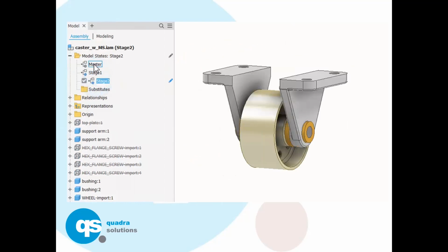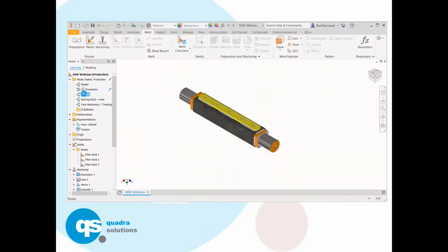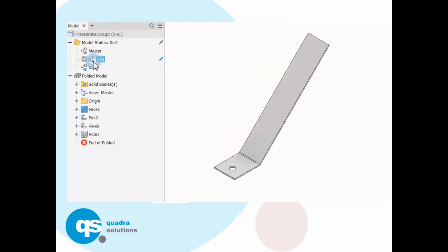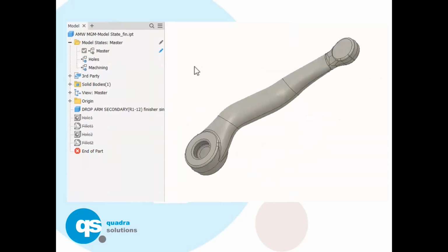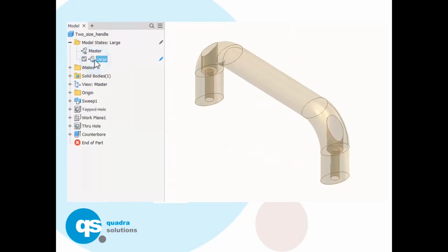We're all driving around in 2 gig 32-bit computers, and if you're building the entire factory, you are going to run out of space. There's not enough memory on that machine to run Windows and Inventor and Excel and everything else that you're driving, then open up a 5 gigabyte super assembly. There's just not enough oomph on that machine. Level of details, if you're working on the factory and you're in the office, there's no point loading the shop floor. If you're working under the hood of the car, what's the point in loading the boot? If you can't load the entire thing, you load the bit that you're working on, a reduced level of detail.